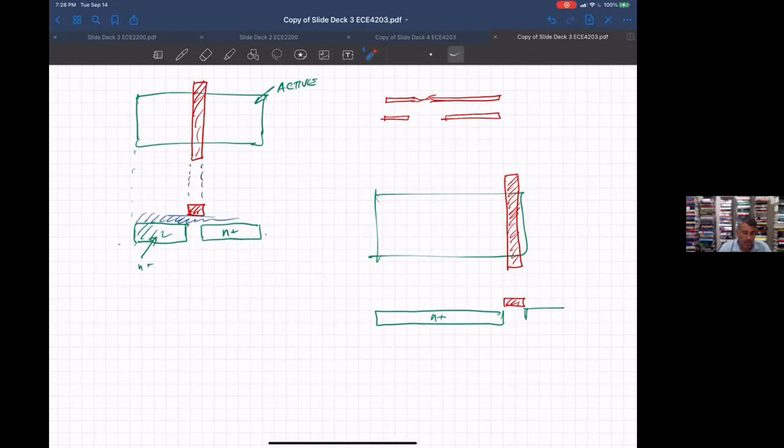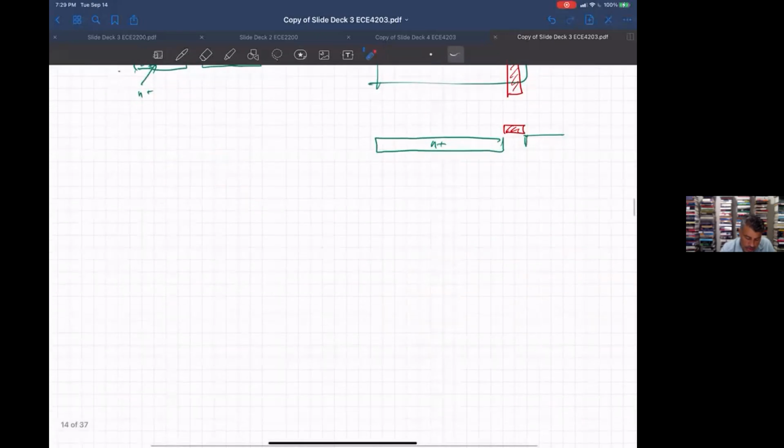As accurate as this equipment is, there'll be some misalignment of these different layers. And if you don't allow enough separation or enough overlap or enough slack, in whichever way you want to look at it, in your geometries for the manufacturer to be able to build this thing, you'll get shorts, get grounds, or more likely you'll get a higher number of defects if you really push things to the edge, right? Some chips will come back and work and some won't.